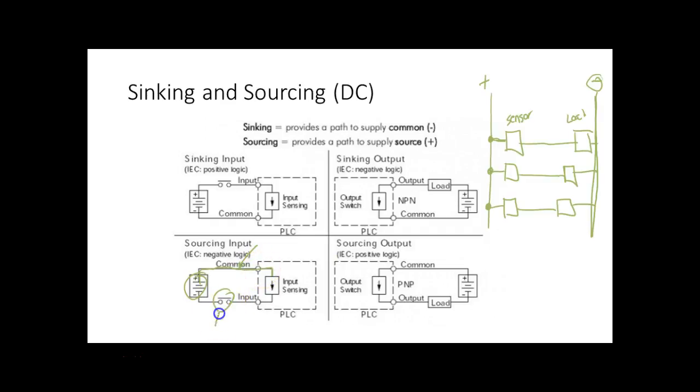So this would be my sensor, representing a digital sensor, right? You understand that? So usually when we use the term digital sensor, we're talking about a sensor that's going to either be on or off. Now, an analog to digital converter is a device that's going to take an analog input and convert it over to an equivalent binary number that represents the weight of that analog input.